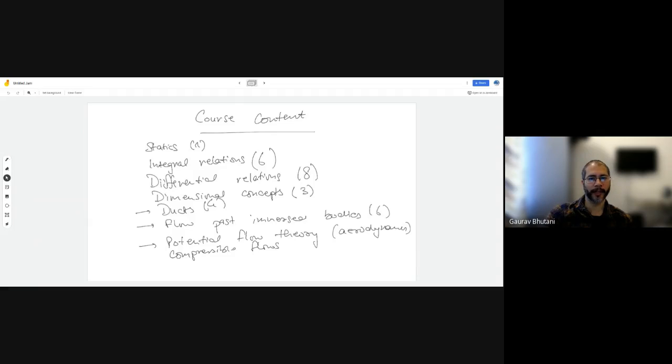I'll give you one quick peek into it. So you have learned about nozzles, right? You have learned that if you have a nozzle which is like this and the flow is happening from left to right, then as the flow goes from left to right, its velocity increases. So the velocity at point number 1 will be less than velocity at point number 2 because it's converging. It's like when you spray water through a tube, you press the surface of the tube to decrease its area so that it can increase the speed.